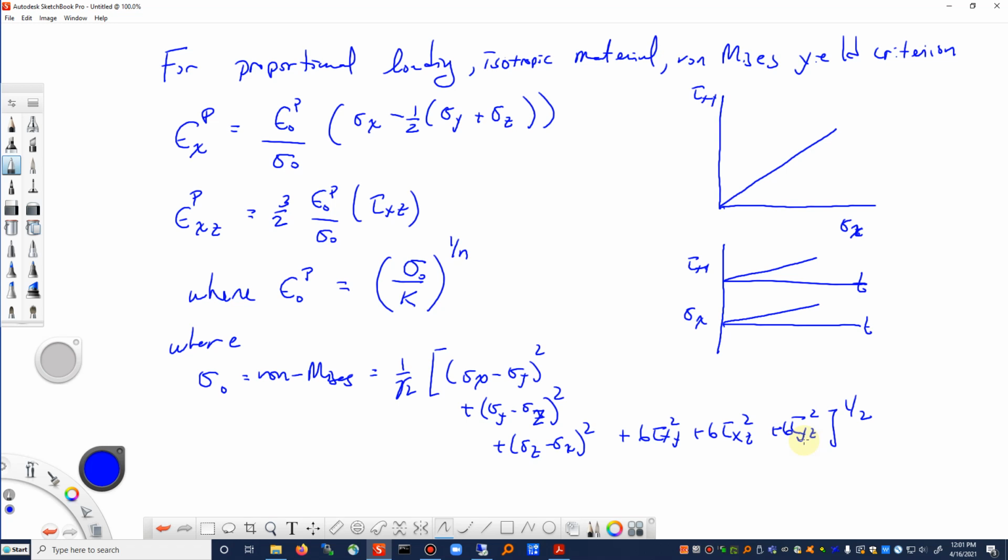All right, so this gives us a way to calculate these plastic strains under what we call proportional loading. If you have cyclic loading, then you can do the same sort of calculations and use strain ranges and so forth, and even the equivalent of the Masing hypothesis. But the key here, and the thing that I want to point out, is what we're basing our plastic strains on is some equivalent from our equivalent stress versus equivalent plastic strain curve.